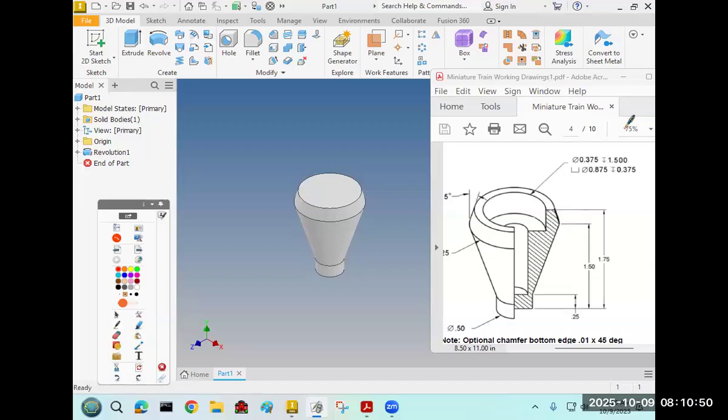First click on the green line, yep, 15 degrees. Okay, and that line, top of everything, go due east, snap it to horizontal. And then finish sketching.